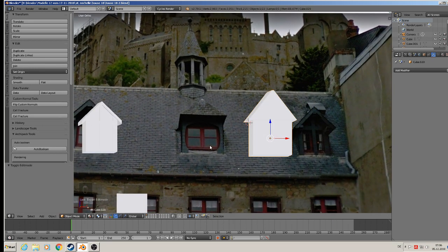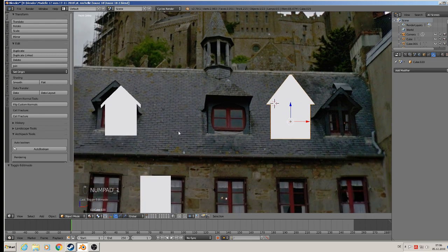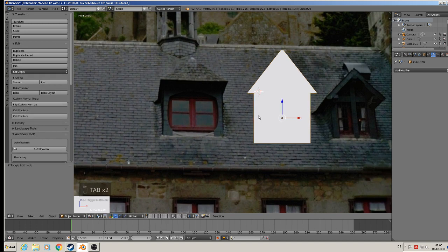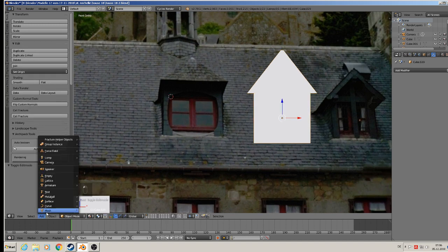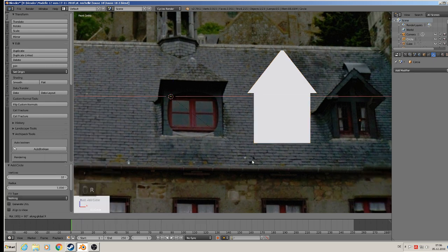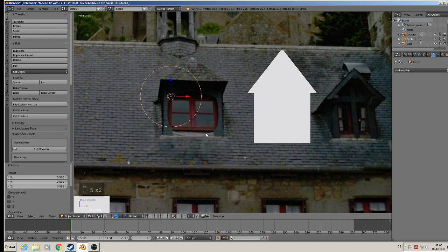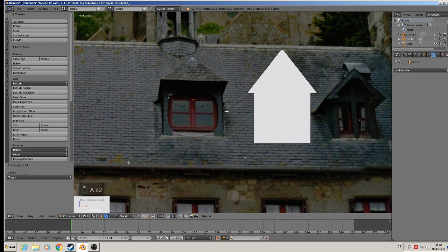Then there must be a rounded hole there. Never seen such, but it's French, so you know what I mean. Good. So we must build that. That means we add mesh circle, rotate X 90, scale down, grab, positioning. To get a good result, normally we take the middle line to fit with them, and then scale set to bring them into position, then edit mode, delete the lower part, and we have that.